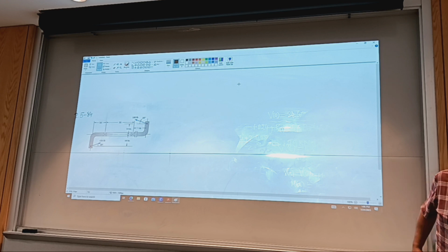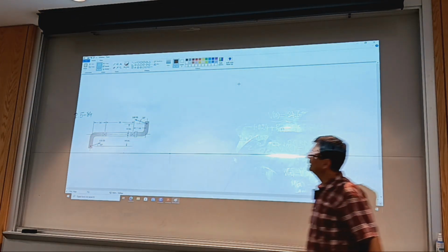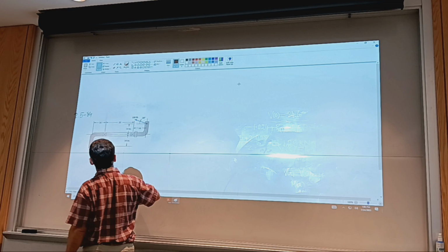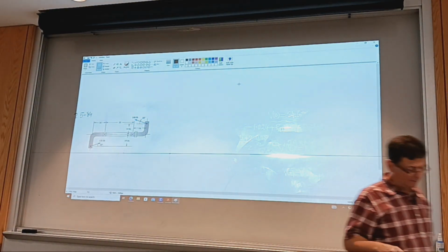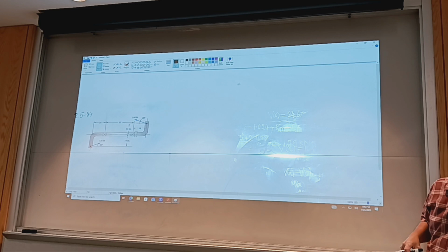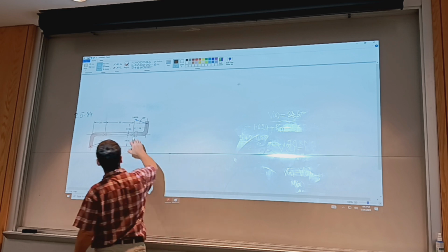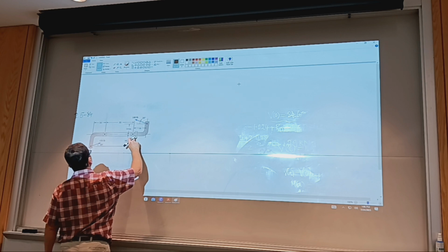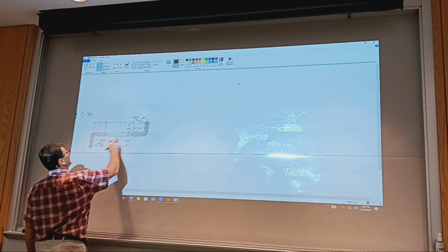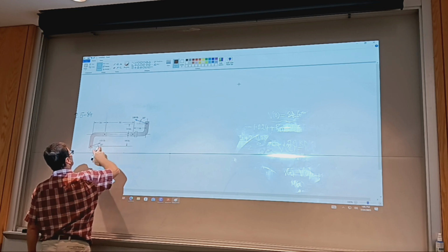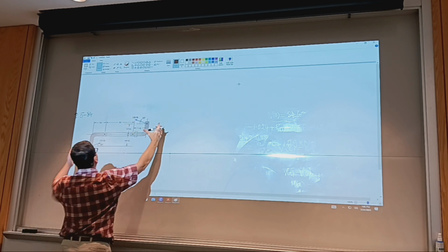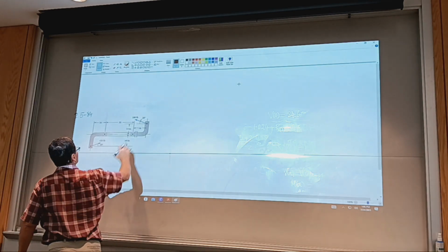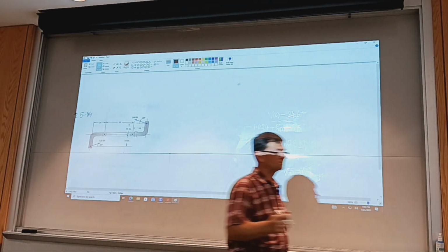So for these problems, with a cross there are bearings, and the bearing that resists thrust, for our case, would be this one. This one resists any unbalance of forces, and there appears to be unbalance of force. I have 20 degrees, one is bigger. The whole thing has a tendency to slide to the right. It will be this bearing that resists thrust.